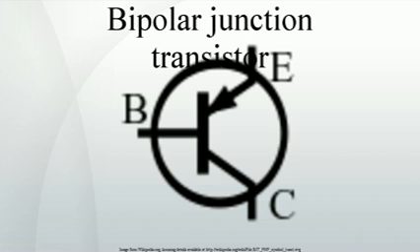Voltage, current, and charge control. The collector-emitter current can be viewed as being controlled by the base-emitter current (current control), or by the base-emitter voltage (voltage control). These views are related by the current-voltage relation of the base-emitter junction, which is just the usual exponential current-voltage curve of a PN junction (diode). The physical explanation for collector current is the amount of minority carriers in the base region.